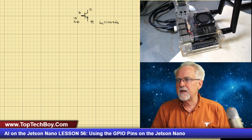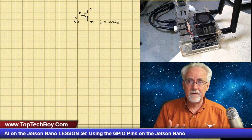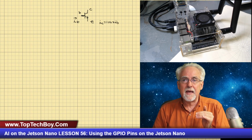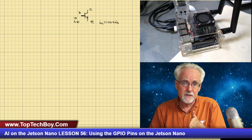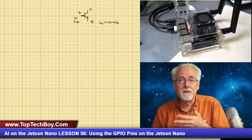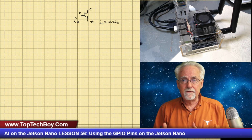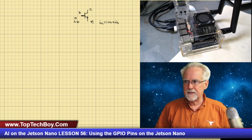And this is how they did amplifiers back in the early days: if you hooked a microphone to the base, that has a very small current coming out of it. You amplify that current through the transistor, and then you have a large current in the collector or the emitter, and you could run a speaker. And so a transistor is used to amplify, or it is used as a switch. And today we will be using it as a switch.